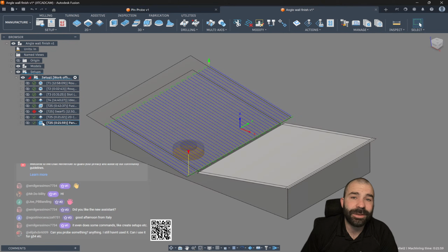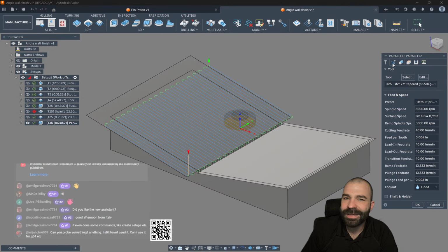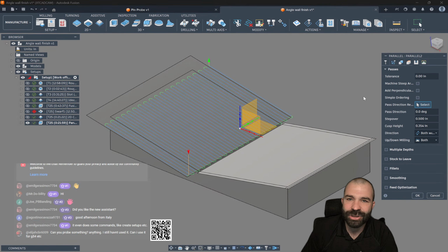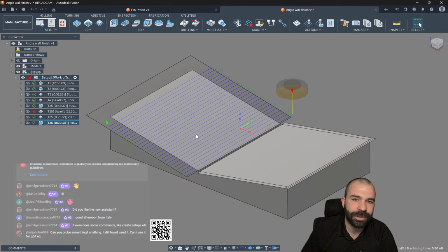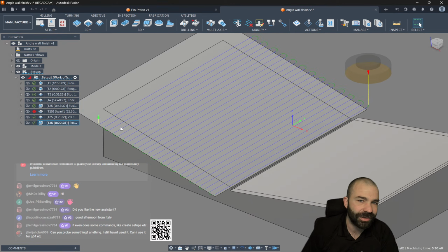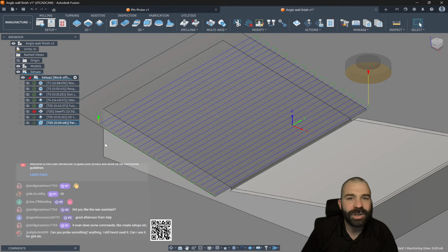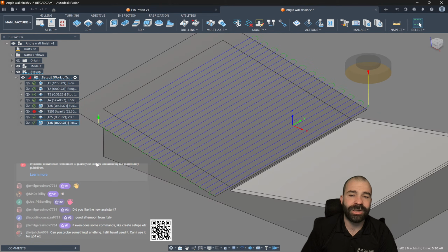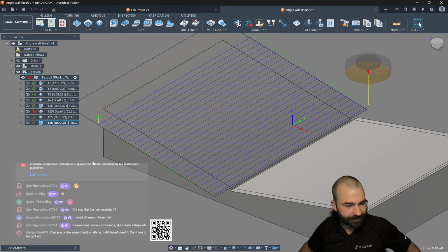Now, as you can see, we need to go ahead and adjust our angle. So let's go ahead and change our pass direction. And just like that, you're going to notice we're now running horizontally with a very exceptionally large tangential extension to get off of our part, turn around, and feed back in, making a nice clean transition as well, reducing chatter and other problems.